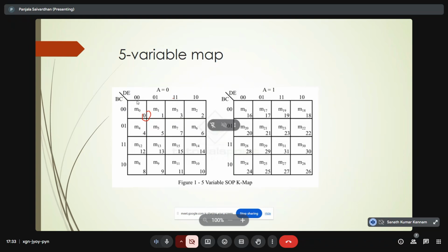Normally with binary you will get 0 0, 0 1, and next you will get 1 0, no? If you take this, it is A bar B plus A B bar. Can anyone minimize D bar E plus D E bar? I think it is not minimizing, no? So in order to minimize, we need to use the gray code sequence. Okay, is it fine?